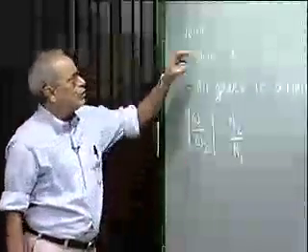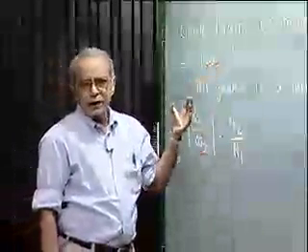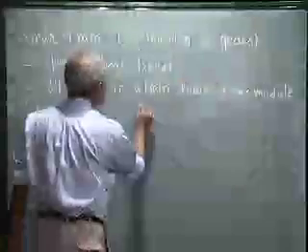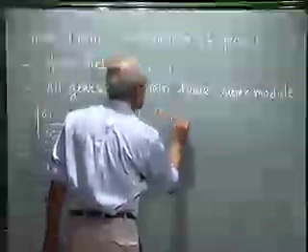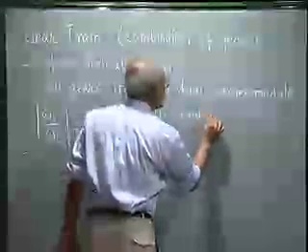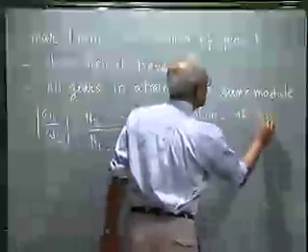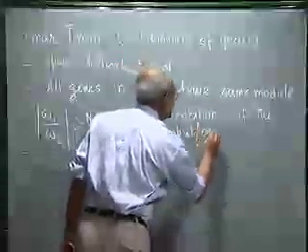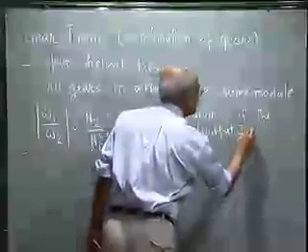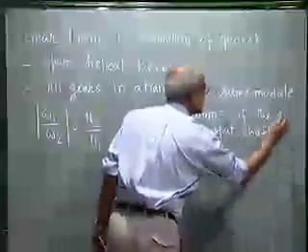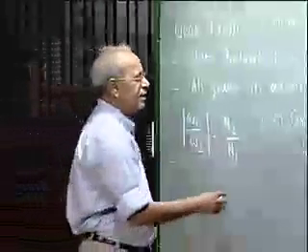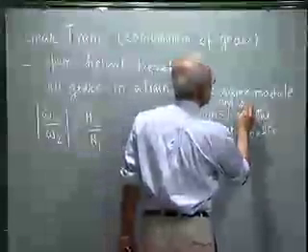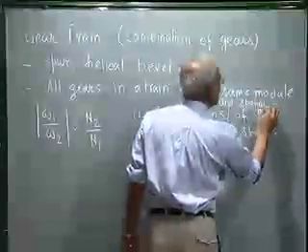Now the question is, why do we need more number of gears to connect a particular input shaft to the output shaft? There may be various reasons for that. For example, the orientation of the input and output shaft. That may dictate that you need to have more than 2 gears. Orientation and placement, the spatial location.